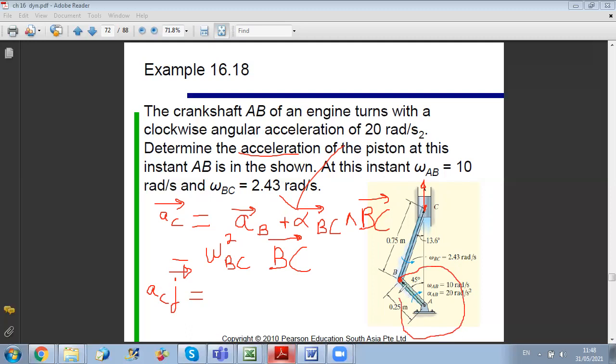B is rotating about A. So since B has a rotation about fixed axis, we can say that AB is decomposed into two components, tangential component and normal component. Now, to get AB, you have two methods. You can do the vectorial relation to relate AA and AB if you want, or you can decompose it into normal and tangential.